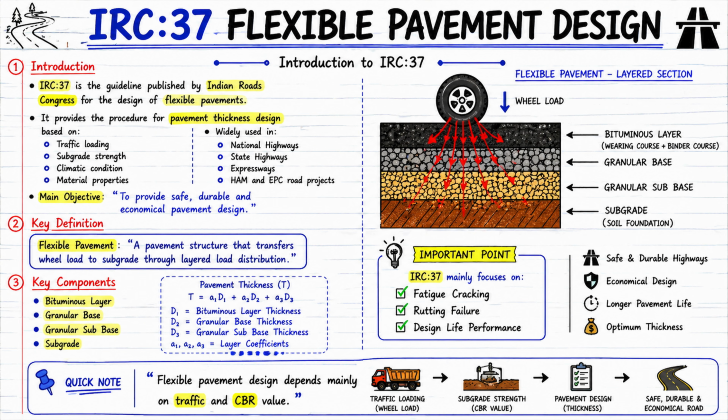It provides riding quality. Provides waterproofing. Receives traffic load. Granular base. Now below is granular base. It provides structural support and spreads the load. Granular sub-base. Now the GSB layer. It supports drainage and protects the lower layers. Subgrade. Natural soil at the bottom. Ultimately the entire load reaches this. And this is why weak subgrade can become a major cause of future failure.